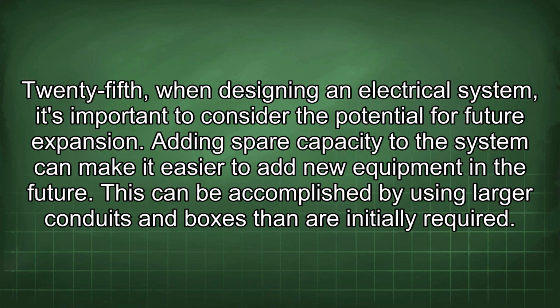25th, when designing an electrical system, it's important to consider the potential for future expansion. Adding spare capacity to the system can make it easier to add new equipment in the future. This can be accomplished by using larger conduits and boxes than are initially required.